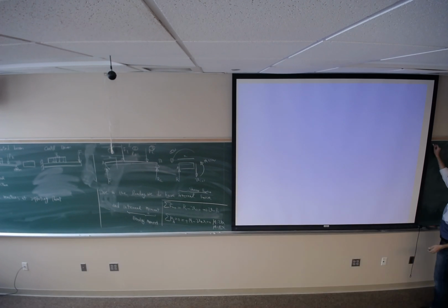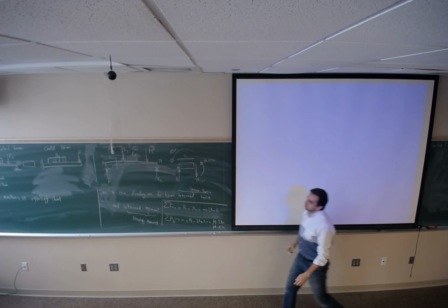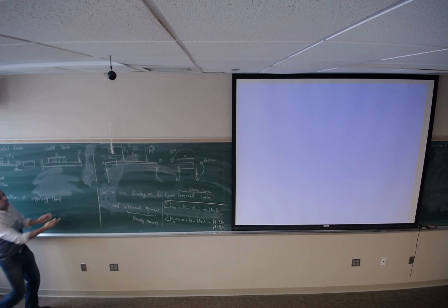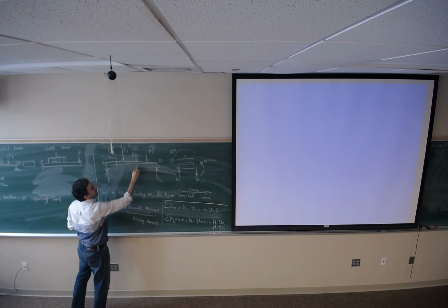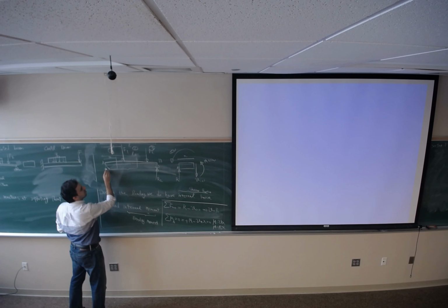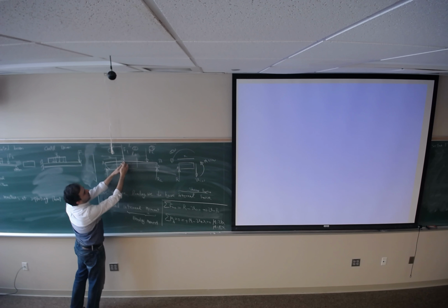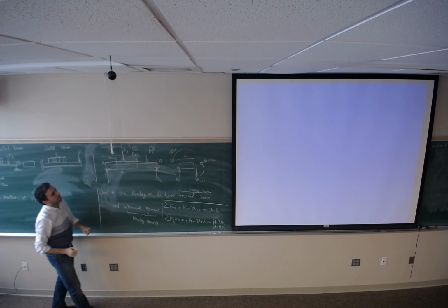So for section 1, V is R1, and M is R1 times X, as I calculated. Now for section 2, I cut it at a distance of X. This X is different from the previous one. It's going to be from L1 up to L2.